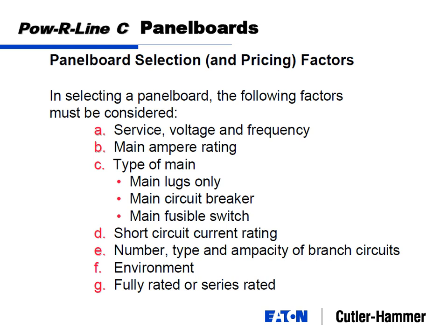In service entrance equipment, what do you suppose the reason is behind having to have some kind of service entrance equipment label on it? It's going to shut power, but who? The fireman. Number one reason, and this is when you build a new building, the fireman's probably going to walk over and the inspector's going to check it, and the fireman is going to look and say, where's your service entrance equipment so I can shut off power to your building when stuff hits the fan.